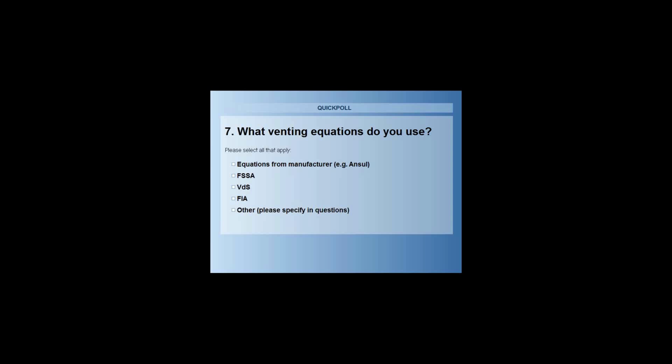So someone asked, how do we determine the positive and negative pressure limits? It's actually based on the wall strength. Essentially, if you say that you've got a wall strength of 500 pascals, that becomes the enclosure pressure limit. Someone said, I don't know what acronyms mean. I'm not sure which acronyms you're referring to. Chances are, if you don't understand them, like FIA or ISO, then you're probably not using it.